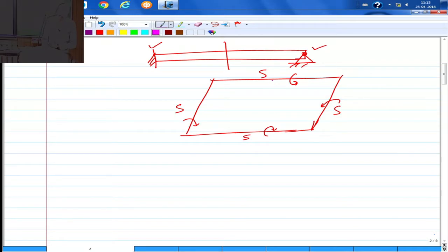In this case again, if you do the modal analysis, the free vibration analysis, you find that because the boundary conditions are symmetric and the geometry is symmetric, you have two lines of symmetry of the structure itself. This entire structure is symmetric about this line, and it is also symmetric about this line. So when you do modal analysis you will find modes which are symmetric with respect to both the structural symmetry lines, or antisymmetric about both lines, or another set symmetric about one but antisymmetric about the other.